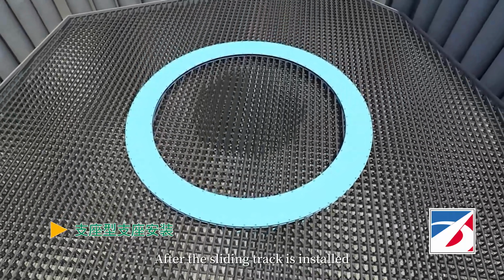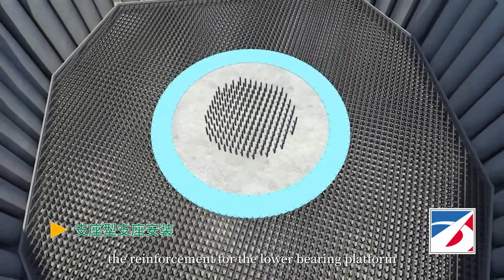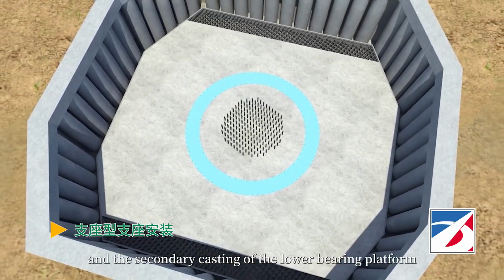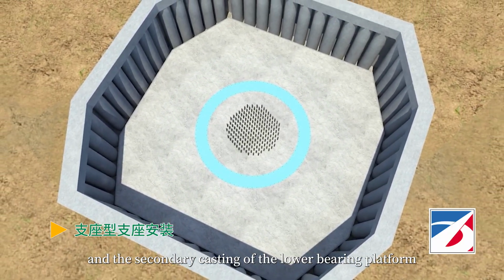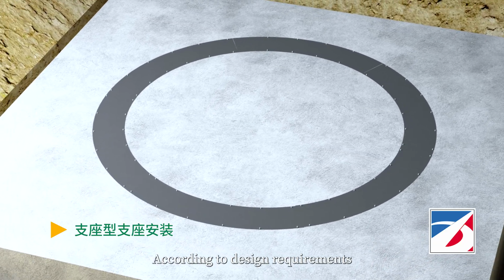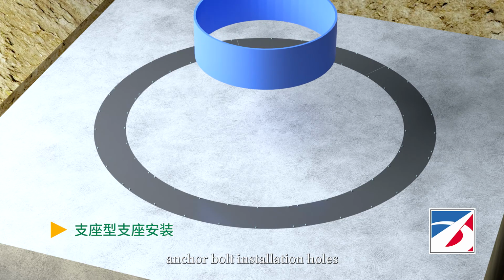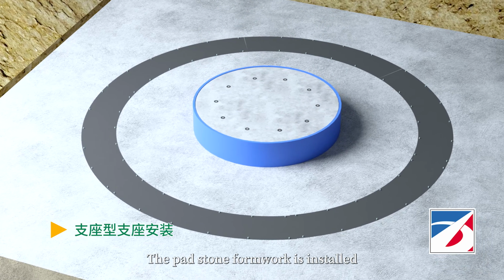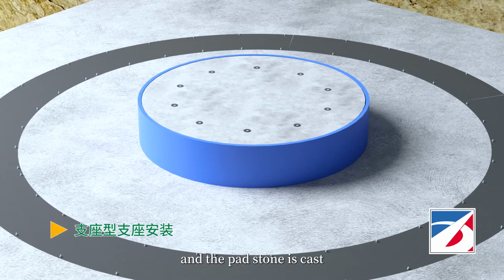After the sliding track is installed, the reinforcement for the lower bearing platform and the padstone is bound, and the secondary casting of the lower bearing platform is carried out. According to design requirements, anchor bolt installation holes are reserved for casting the padstone. The padstone formwork is installed, and the padstone is cast.